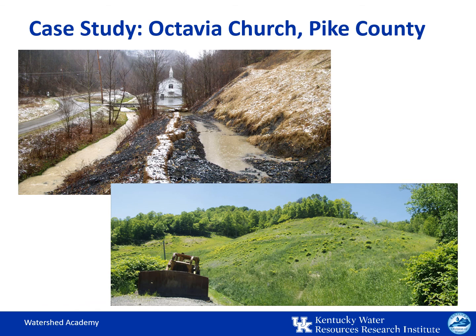Through the AML reclamation project, an existing sediment pond was cleaned out and the dam spillway was repaired. A berm along the edge of the creek and diversion ditches were lined with rock or erosion control blankets, and they routed runoff to the cleaned out sediment pond. Coal refuse was removed from the creek banks and sold at marketable value. Then the area was covered with topsoil to at least 2 feet deep. Drainage was further controlled with additional hay bales, berms, and diversion ditches, and the whole area was revegetated.